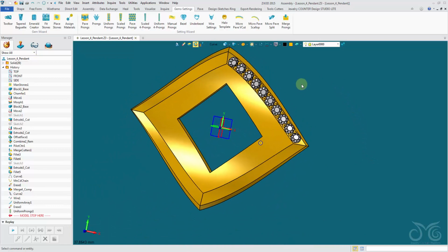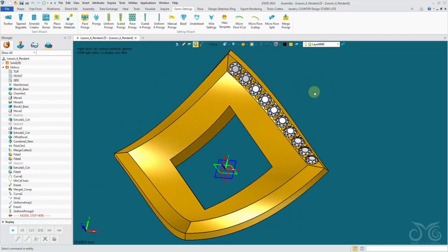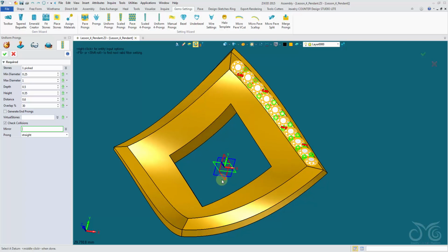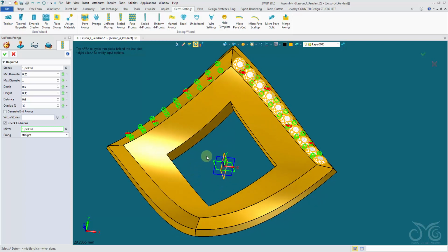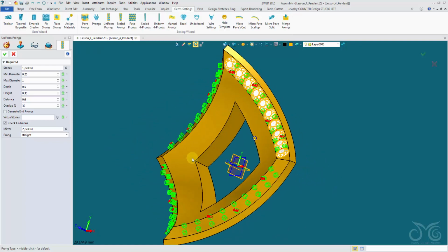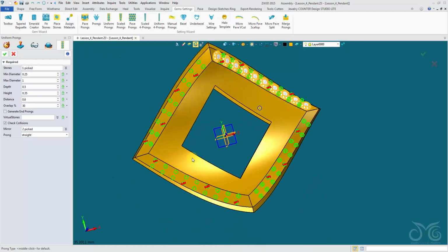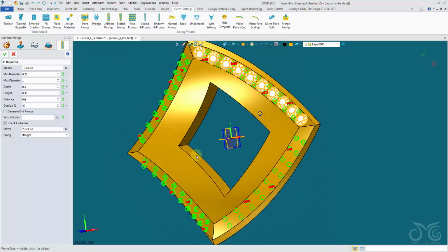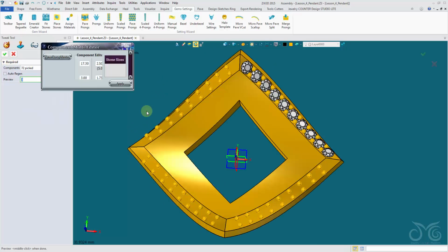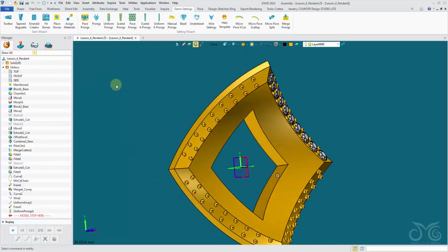Okay, but what I should have done is made use of the mirror tool within that prong command. So I'm going to redefine last, and I can use this mirror here. Okay, so this mirror allows me to mirror my created prongs across 2 datums, or even more datums than that. So here we're getting the mirrored copies of these prongs. Confirm the operation. New tweak. Okay.